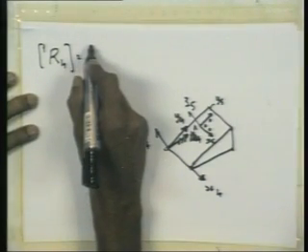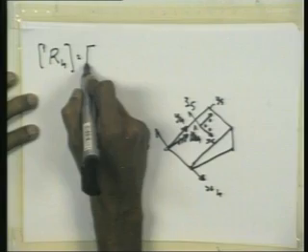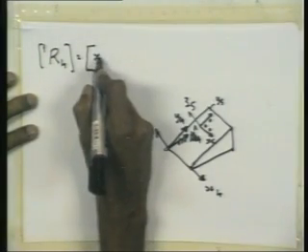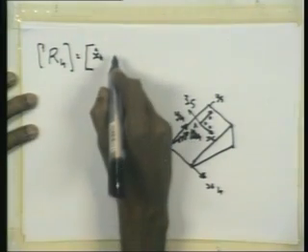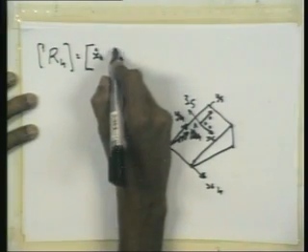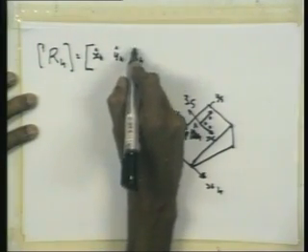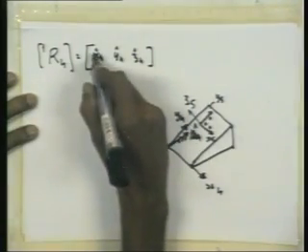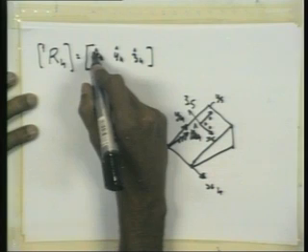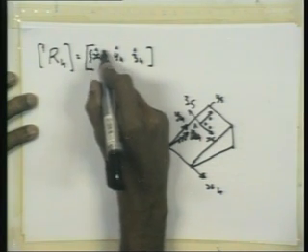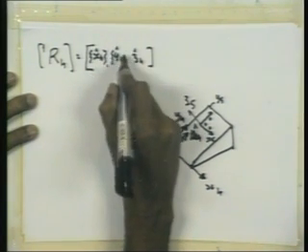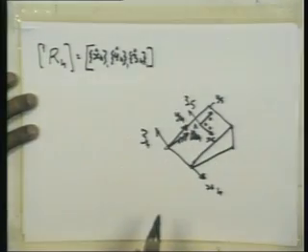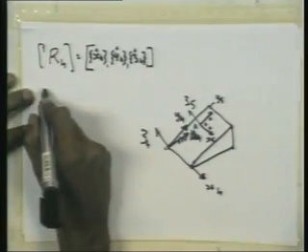So if you look at this, you will see that it consists of 3 columns: the unit vector along x4, the unit vector along y4, and the one along z4. These are the 3 columns, each of them expressed in the global reference frame. Right. So what is x4?